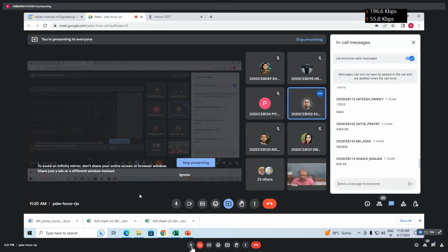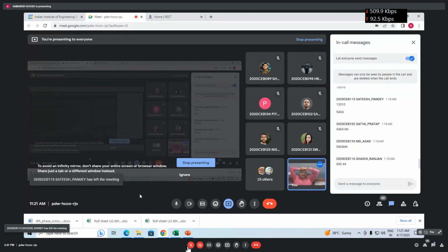Sir, in case of the pile group, we have calculated one in group and one for single. So can this happen that individual is higher than the group one? In this case, we got individual is higher, no? We will take the minimum. We will take from the minimum, whether block failure or individual failure, which one will be minimum, that will be taken.